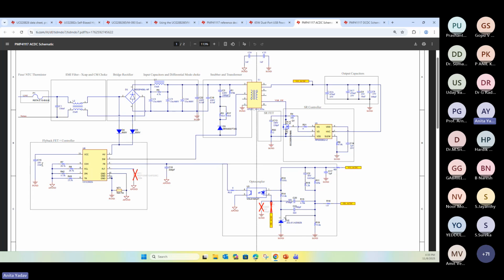So accordingly all the registers are selected, then VCC is generated inside, and for this cap on the VCC pin, it's preferred to use X7R series capacitors because those are rated for 125 degrees Celsius temperature, if I'm not wrong. The value of the cap is preferred in the range from 10 microfarad all the way to 47 microfarad. And these two are Schottky standard diodes connecting directly to the HV pin and acting as a full bridge rectifier.